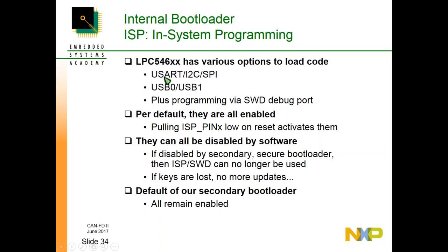And if you used on-chip bootloaders before with UART, then the others work similarly here: to activate them, you pull a certain pin low, and that activates them, not just during a reset, but after a reset. So if the device comes out of reset, sees that one of these pins is low, the bootloader is activated and it remains in this bootloader. This means as long as this mechanism is in place, you always have a backdoor.